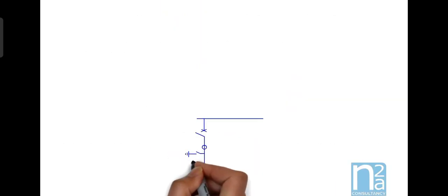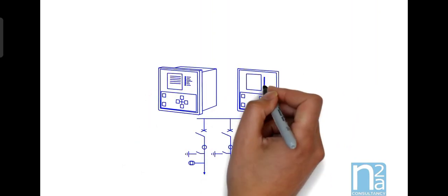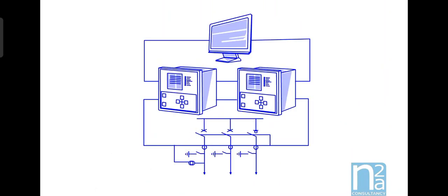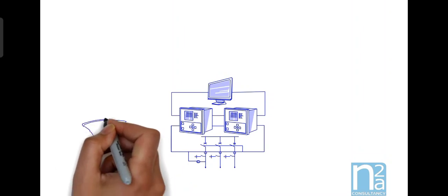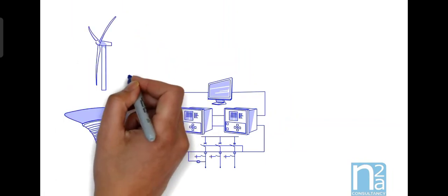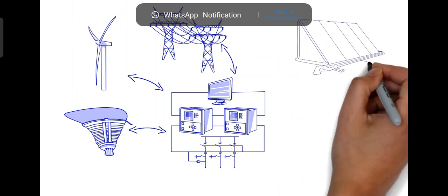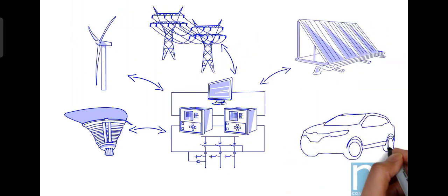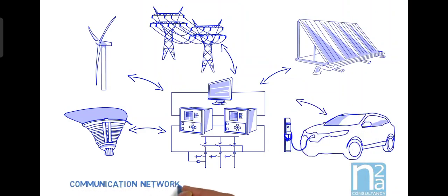The first edition of the IEC 61850 standard was called Communication Networks and Systems in Substations, and was focused on communication at power substation level, between relays, substation control and switchgear, to provide interoperability between functions from different vendors. It was so successful that it was quickly extended to all network functions and domains, like hydro generation, wind turbines, distribution automation systems. Another domain, like electric vehicle charging, is under development. It is now called Communication Networks and Systems for Power Utility Automation, and its scope is continuously growing.